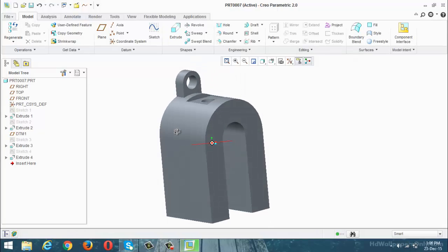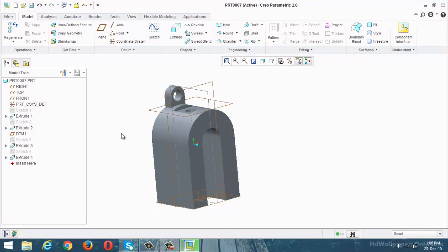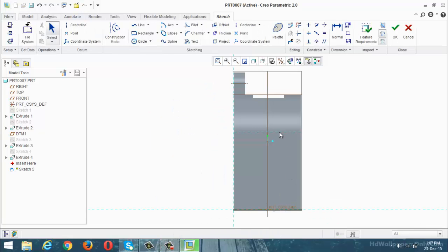Next one. Again, how to design the next one? Activate this reference. Now the rectangle starts from this edge onwards. Directly you can design one rectangle in this format. Again how much height? 14. Height equal to 14 and length equal to 48. And that is the symmetrical location. 14. Again this is the 48. Again no problem. Select this center to this one, it is the 24.